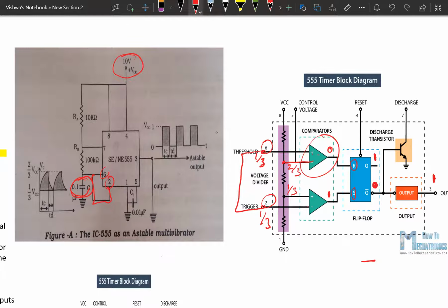That means the negative terminal voltage now becomes equal to or greater than the positive terminal voltage. In these conditions, the output of the comparator becomes 0, and the state remains the same. The output stage also remains the same. There is no change in the voltage until the reset input changes. So again Q bar is 0, the output is 0, then the output is high only.